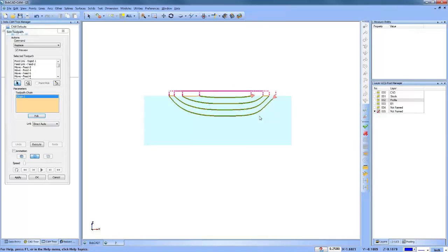All right, so some of the things that you're going to want to do is maybe control what direction it's cutting in and things like that. So if you go into the Toolpath Chain dialog, you can right click here and you can delete all, modify start point or reverse direction, just like you would have modify start point or reverse direction on a standard profile. Okay, cool. All right, so now we're going to do a reverse direction to make sure that we get it cutting the right way. So it's going to come down this way and work that way, and away we go.